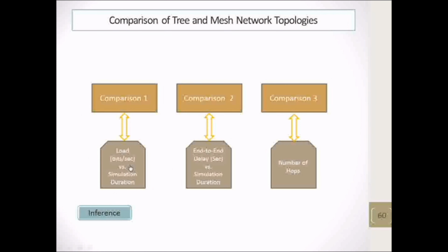From the monitoring area to the forest area we require 3 signals, that is asterisk, at and hash, for the thermistor or temperature sensor reading, pressure sensor reading and rain sensor reading respectively. That is, in order to fetch the temperature sensor reading we need the special character asterisk. If we send asterisk, it will go to the forest area module, fetch the readings associated with the temperature sensor and return them.